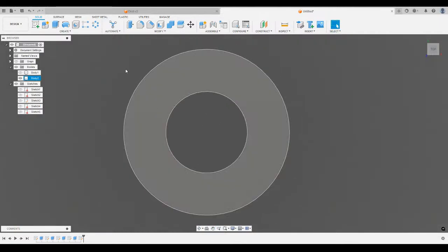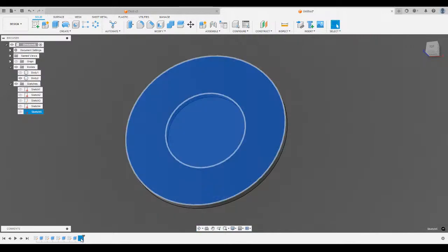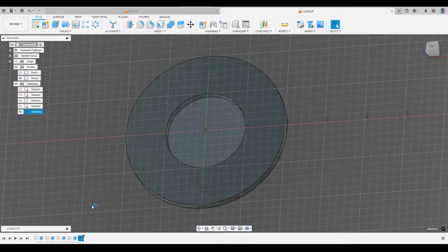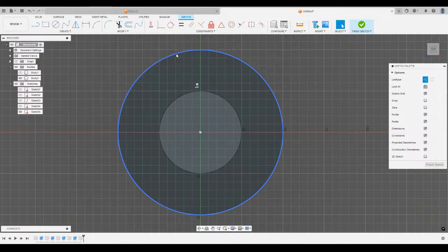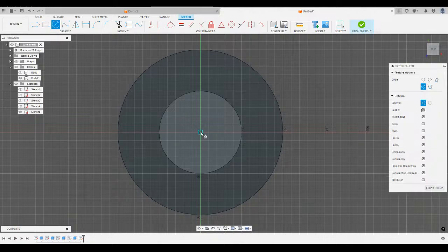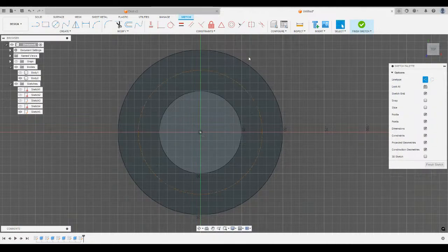So I got this disc shape here, or this washer shape here. So I'm going to go back to the sketch that I started, and I'm going to turn on construction, and I want a circle. I'm going to use offset. Actually, I said I wanted it to be centered between these. So if I draw another circle right here, there's a few ways you can do this, but I believe if I draw this circle and then I use the symmetry constraint, I should be able to click on...